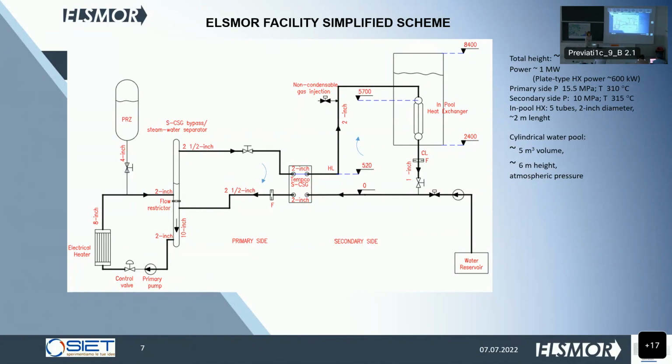So this is the natural circulation loop. And what we are going to verify is whether this combination of plate heat exchanger and vertical tube heat exchanger and the whole loop are adequate for this goal, to remove the decay power from the reactor.